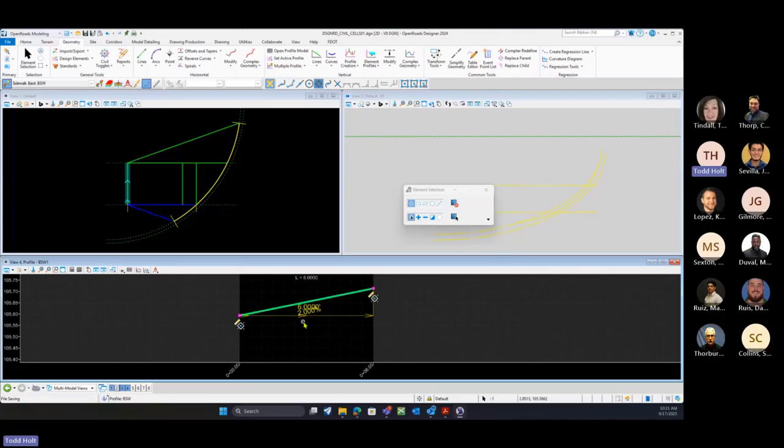So when you're establishing your profile intersection snap, let the software snap to your intersection points. Don't do a hard snap to those. Does that make sense to everybody? Yep. And then I'm going to set this as active. And there we'll see our cross section there for the profile.